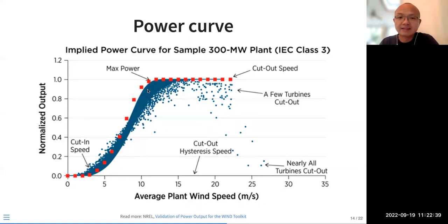As you can see here, when wind speed reaches more than 10 to 12 meters per second, it reaches maximum power. You cannot keep going as in the cubic relationship. So in the simulation, it's very important to use the power curve of a specific wind turbine, and those you can get from the System Advisor Model, the same model I mentioned in homework two.